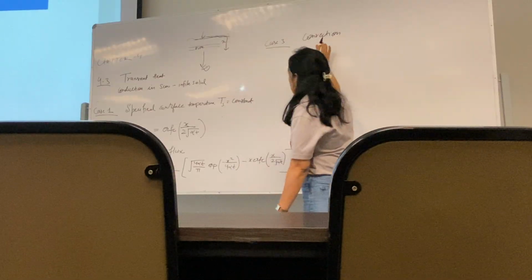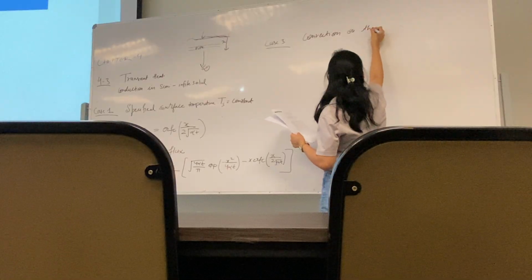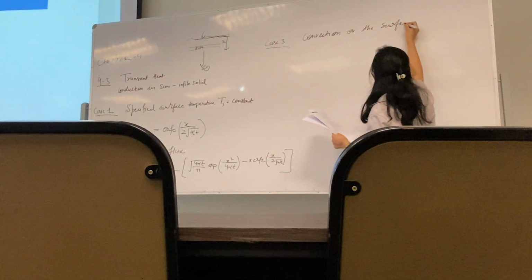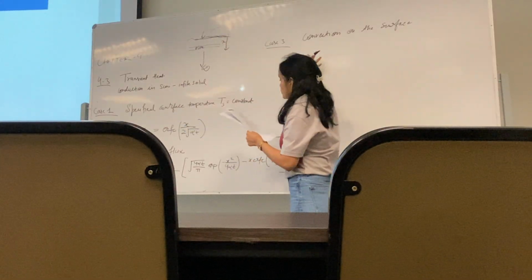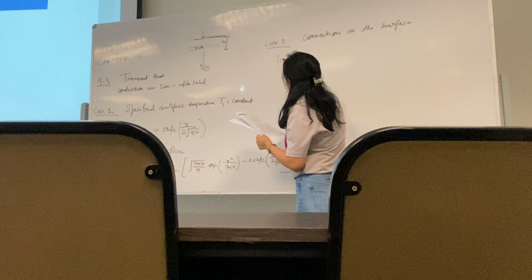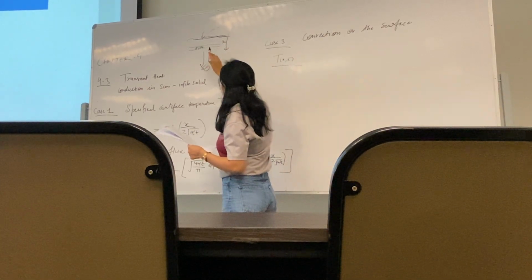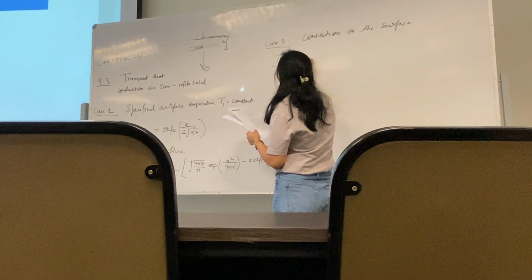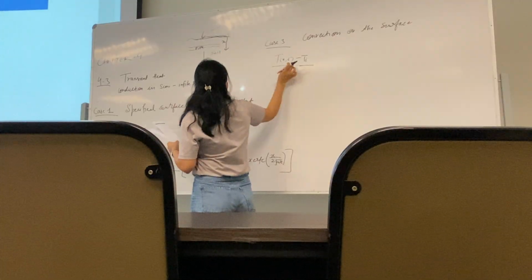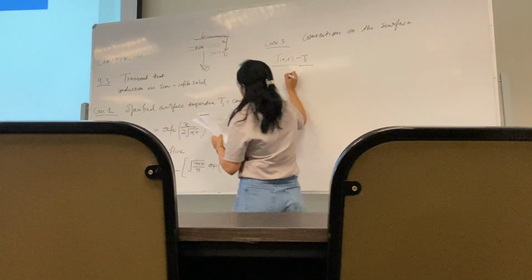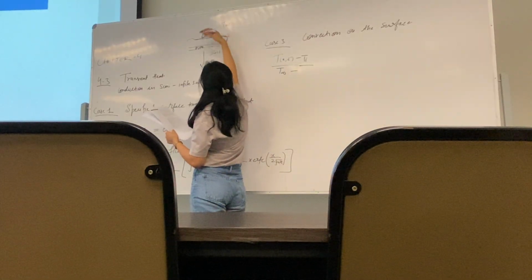If on this surface there is a convection, constant convection, due to wind or water, whatever, you use this formula. They are asking you the temperature at some point here, this pipe here. That is T(x,t). Ti, in this case, let's say this is soil, so Ti is the temperature of the soil. T infinity is the temperature here of the air.